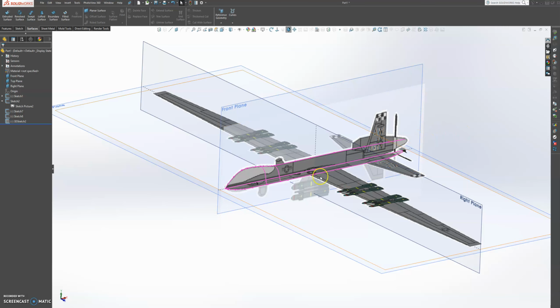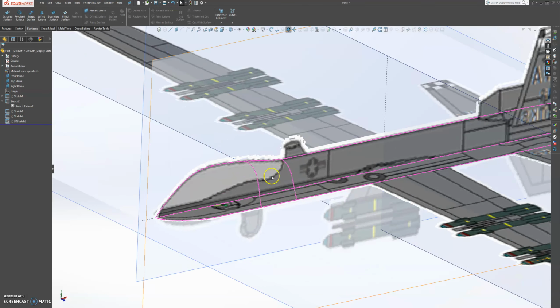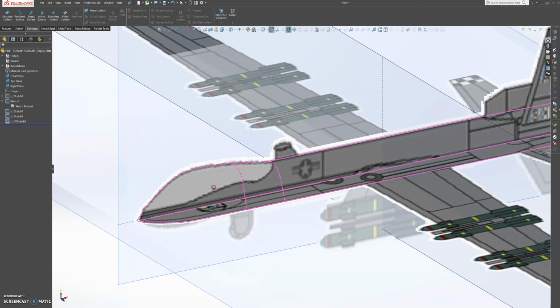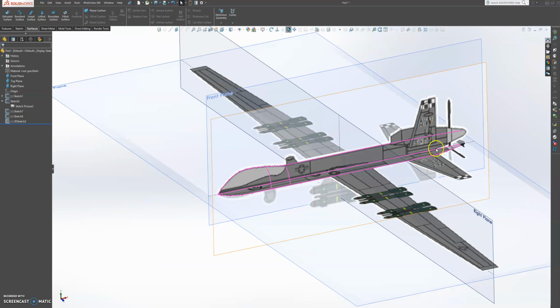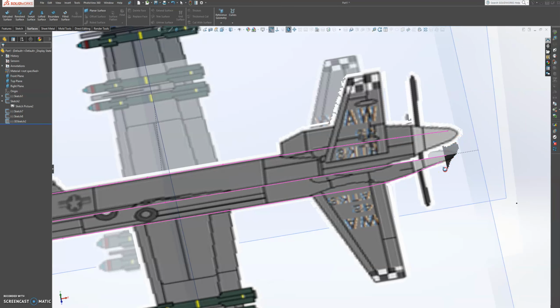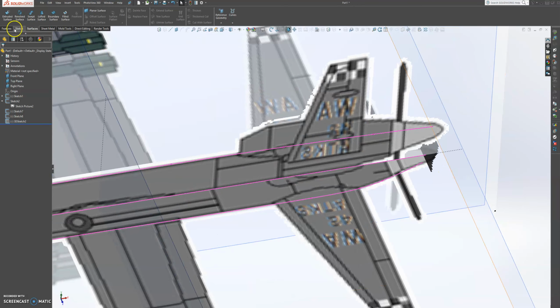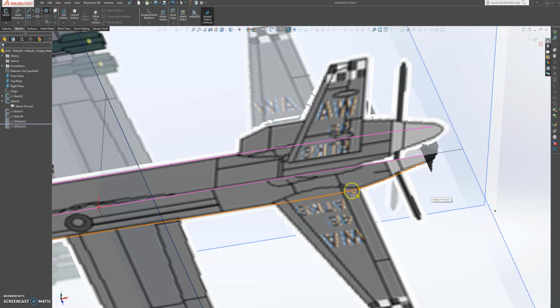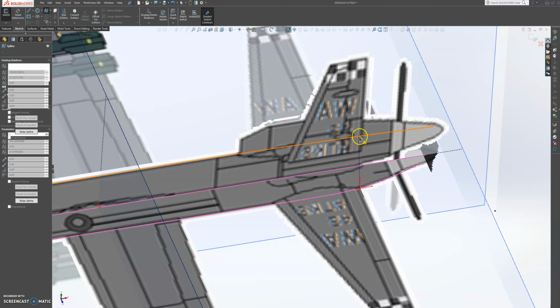So let's continue. We created these two splines here, and then I think maybe we're going to create a few more back here as well. So let's add another 3D sketch somewhere around here, and let's grab a spline from that, and we're going to add that about here where the little curve is starting.